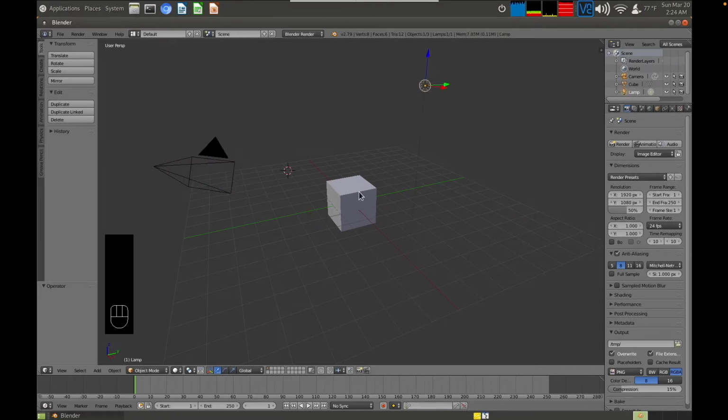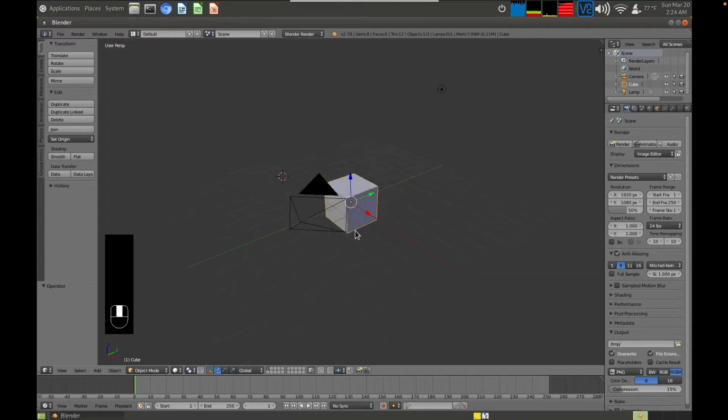Okay. Now, what I'm going to do mostly for right now when we're talking about navigation is select the cube as our reference point. One of the things you can do to actually move around this scene is to orbit objects. So to orbit this cube, you can press the middle mouse button or the scroll wheel. You can see that it's highlighted there, and move your mouse around to orbit around the object that is selected. Okay. You can see down there in this indicator, again, is showing which buttons I'm clicking.